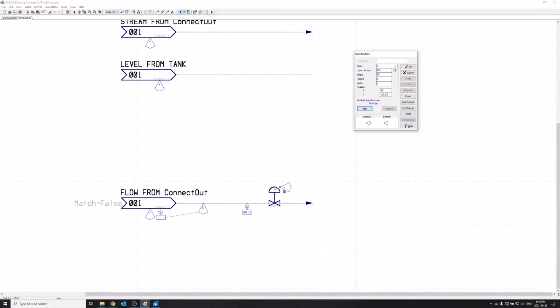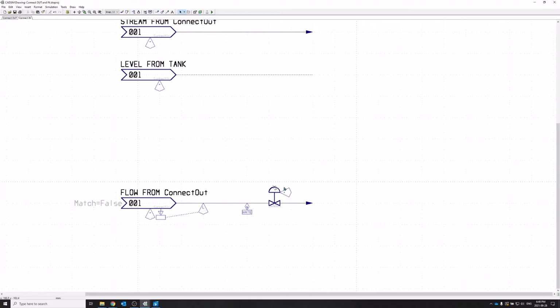And it looks like this guy is hovering here, but it's along the polygon. Let's just drop it off a little bit here. And directly above this valve, let's center this valve a little bit here. Let's use a half snap. So right above this valve, I'm going to add a controller. So that's where I want it to show up.